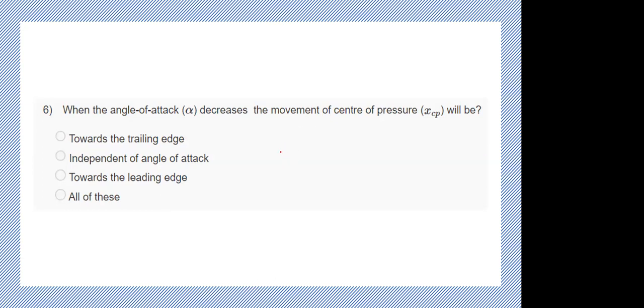Yes, ma'am. The reason is that, if we see through the diagram, if the angle of attack increases, it usually hits the leading edge first, if it's more. But as we decrease the angle of attack, it will start moving towards the trailing edge, ma'am.